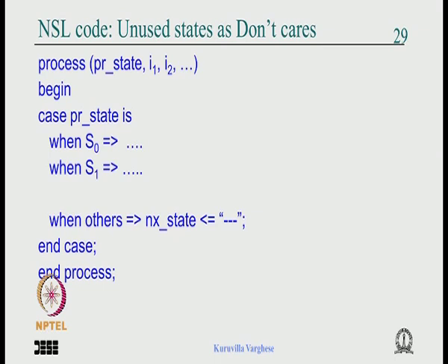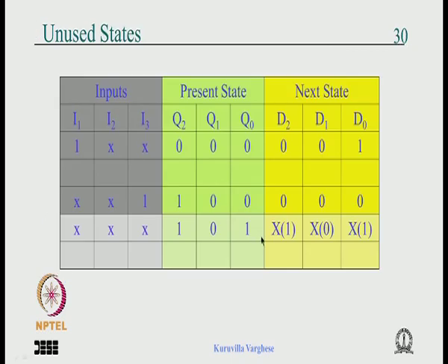That is why we say next state is don't care, and that also shows the use of that particular don't care, because when we discussed std_ulogic and std_logic we said there is something called don't care, and we have not seen it being used, but this is the way it is used, and we are hoping that it gives reduced area. So let us look at one condition, one possible assignment the tool makes.